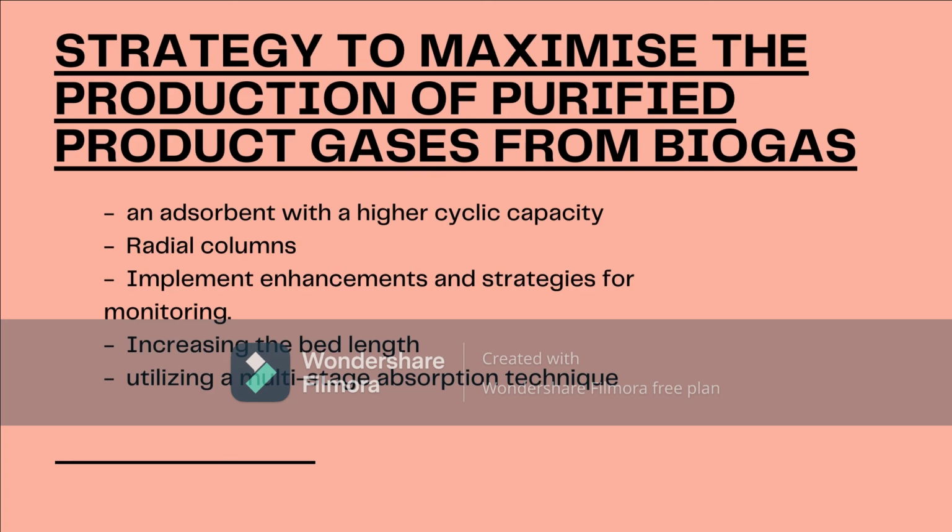Then there are the strategies to maximize the production of purified biogas. Firstly, we suggested using an adsorbent with a higher cyclic capacity.